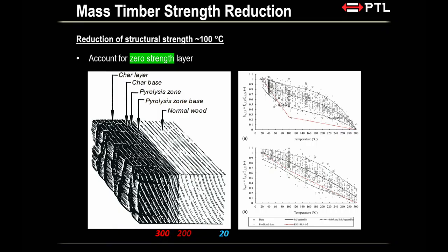Slowly. Slowly. Okay. But still, the thing is, you don't have to go for fire rated adhesive. I mean, in certain situations, you will see when I talk about the Timber Unlimited guidance, there are certain circumstances where you absolutely must have it. But as an engineer, you can also design so that your charring is not so extensive that it reaches your glue line. If that doesn't happen, then no worries.